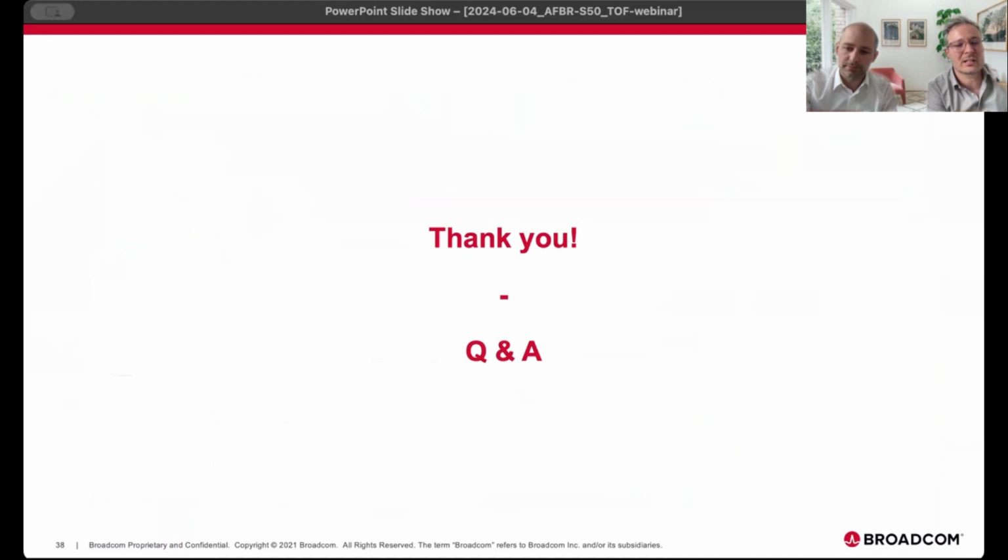You can start working right away. There's just one application-specific case where you need a calibration. When you do a cover glass calibration, you have your own mechanical structure and your own cover glass, and this is where you actually need to calibrate. But we have two application notes which really support you here: the cover glass calibration guide and the crosstalk application note.